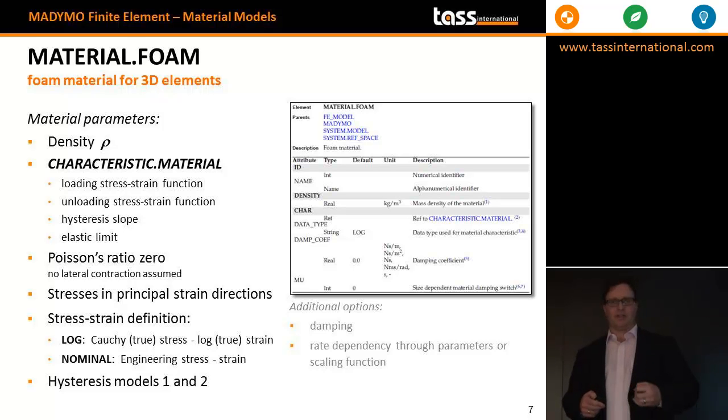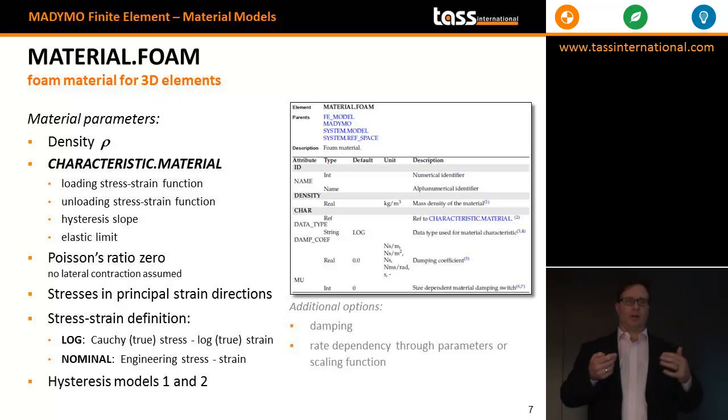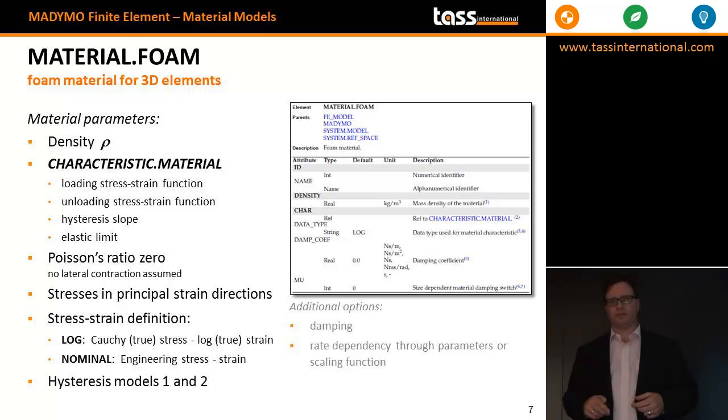The stress-strain definitions specified for the loading and unloading curve are either given as true stresses versus logarithmic strains, or nominal, the engineering stresses versus engineering strains. Furthermore, only hysteresis models 1 and 2 can be used for this material.